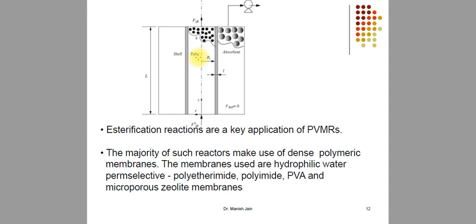So you can shift the reaction equilibrium up to a higher conversion. The membrane used might be hydrophobic or hydrophilic. If you are removing the water, then it might be a hydrophilic membrane. If you are removing the ethanol, it may be a hydrophobic membrane.